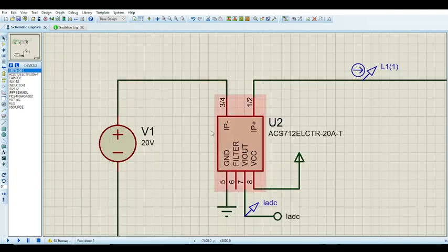In this configuration, the way it is, you're going to have to take a closer look at your sensor board if you're using this particular one, ACS712 20 amp variant. You have to connect it in this configuration, because whatever voltage you sense, the more the current flowing through it, the lesser the voltage on this pin is, the VIOUT. As a baseline, there's a voltage offset of 2.5.